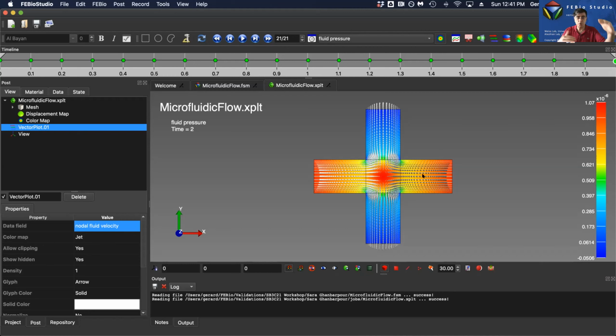And now, of course, you can create a domain which is not a 1 millimeter channel, but a domain that's maybe 2 or 3 diameters of your sphere. And you can even make it a 3-dimensional domain, because that's what it is. You have a sphere. Then you have to apply boundary conditions that prevent rigid body motions of the sphere. So you would have to constrain a few nodes judiciously.